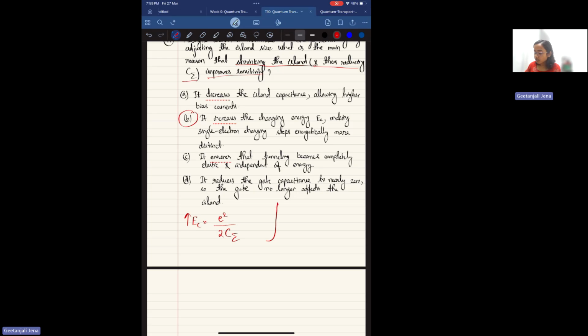The oscillation will be sharp for the design where the charging energy is much larger, and the separation between peaks is also quite large. So these peaks don't overlap, and we can still single out the charging and discharging events. So this is the reason why you can shrink the size and improve the sensitivity.